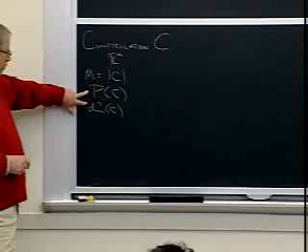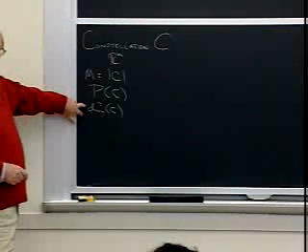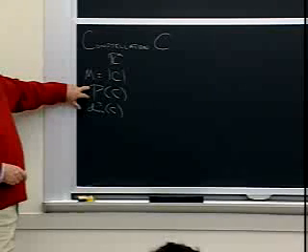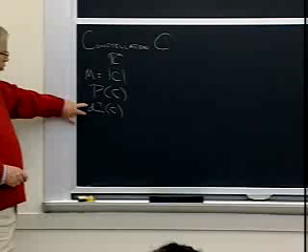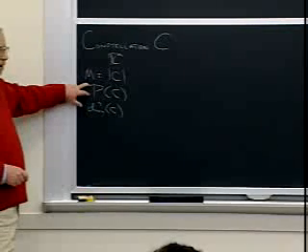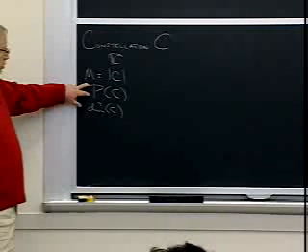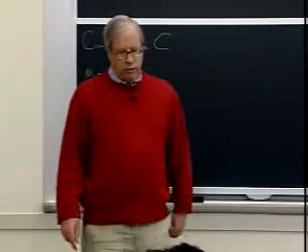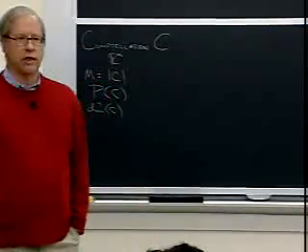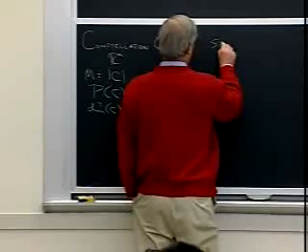Clearly, if I take a given constellation and I scale it up, I'm going to get better minimum square distance, but at the cost of increasing power. So I either fix the minimum square distance between points and try to minimize the power, the average energy over the centroids of a bunch of spheres, or vice versa. So when we do this, this is the game. We get into a classical problem called sphere packing.